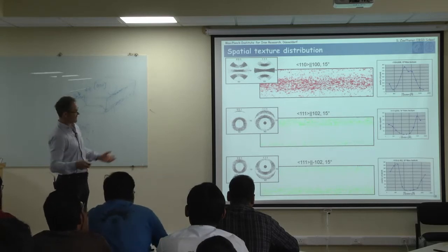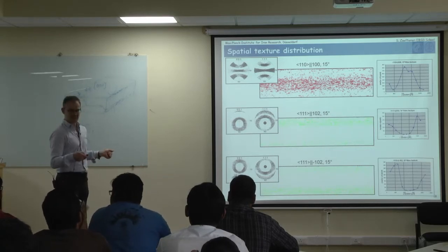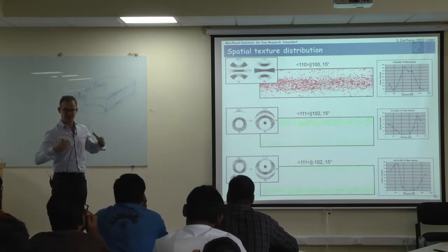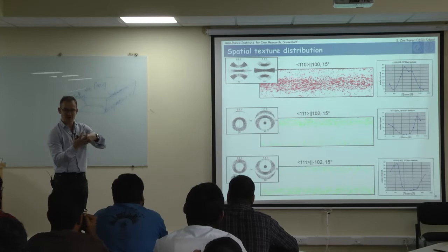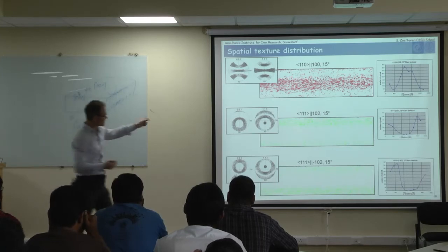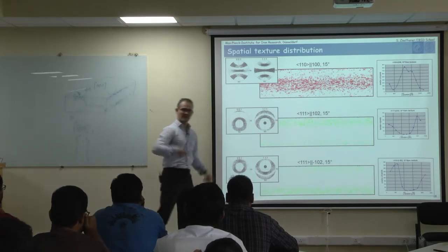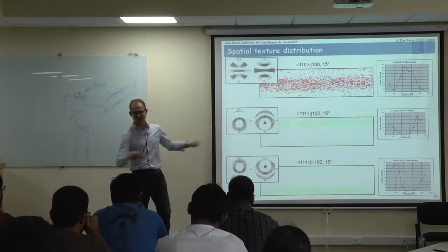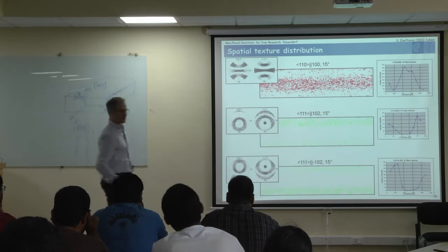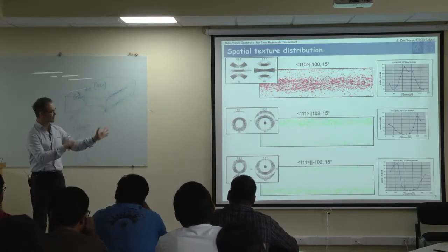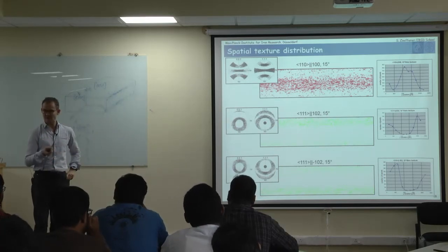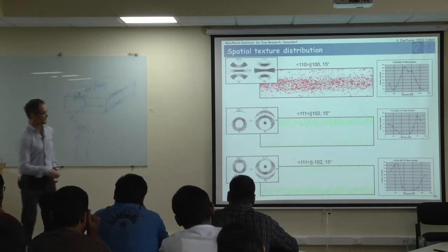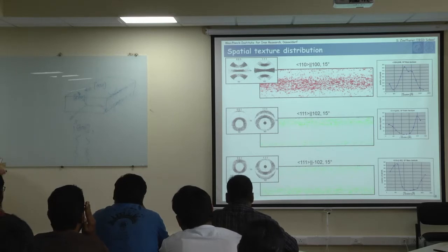When you are at higher temperature, usually the shearing becomes stronger because there is more sticking of the rolls on the material. Then the shear becomes stronger. And by better lubrication it becomes lower. So you take more water into the rolling mill, you will reduce these things. And this could have, here I don't know, but it could have very important consequences later on for the final rolled sheet and for the final product properties.